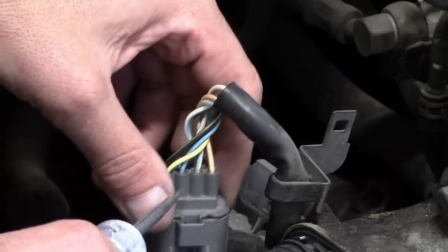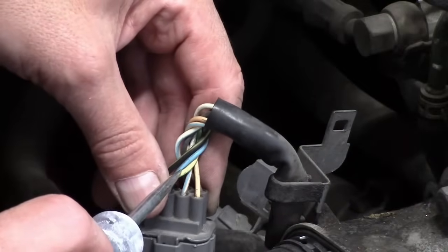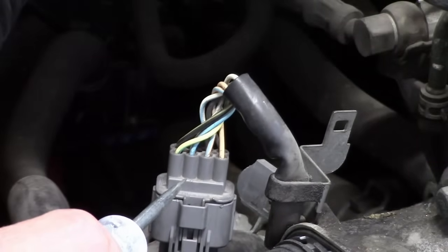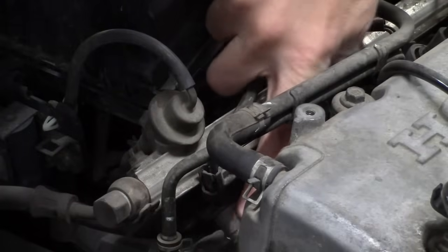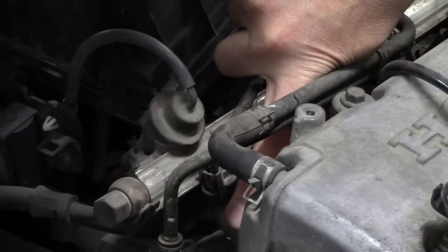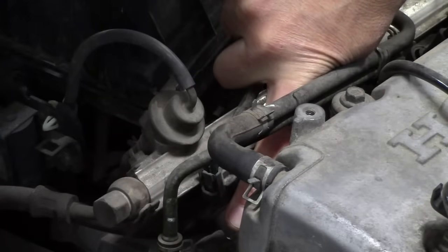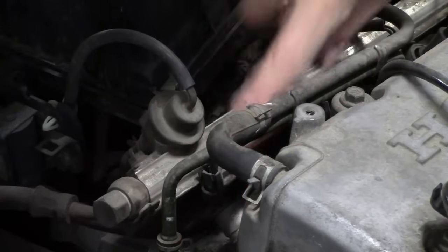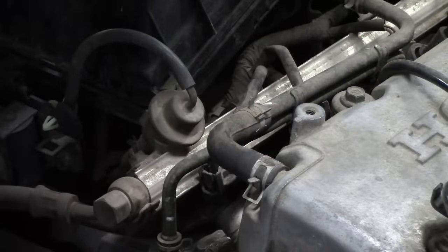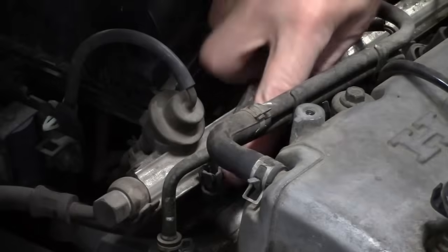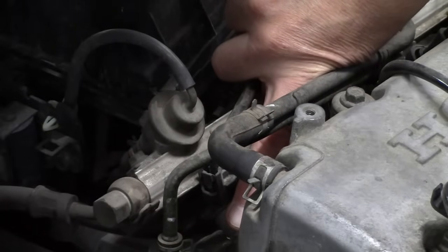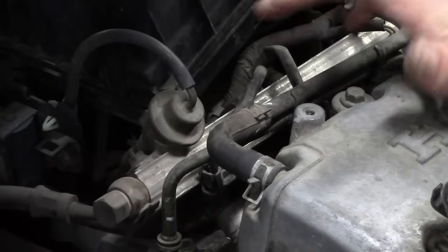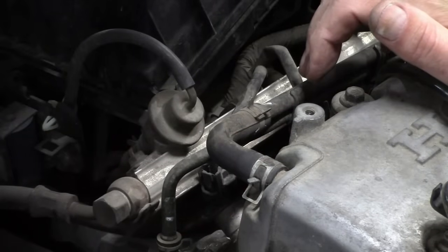What I wanted to do was confirm my suspicions by seeing whether there was any fuel injector signal. The way that I did that would be different than what we're going to do now. Got our fuel injectors right up here. I can actually touch them. So I just held my finger on a fuel injector while he cranked it, and I could not feel any pulsing in the fuel injector. So we've got no fuel, at least I think. It's a little hard to tell that way. We'll do something more definitive. But I believe we have no fuel. I believe we have no spark. Obviously going in the direction of a crank or cam sensor issue.